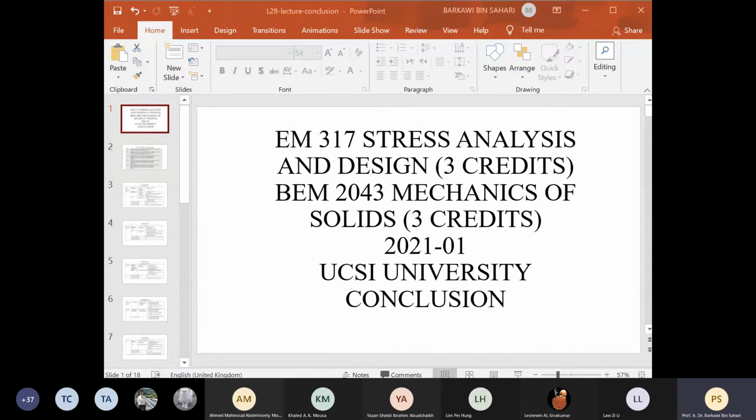If it is the same as in your assumption, then the direction and the value are correct. If the sign of the value is opposite to that in the assumed direction, then the direction is the other way around. At the end of the day, if it is compressive stress, it is compressive, whether you initially assume it is tension and it turned out to be compressive with a negative value. If you initially assume that it is compression, then you will get a positive value at the end. Positive means it is the same as your assumption initially. Negative means it is the other way around from what you first assumed in your free body diagram. So I'm looking at the understanding of equilibrium in most cases.